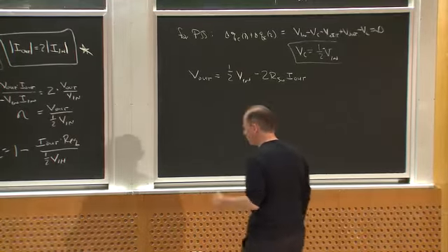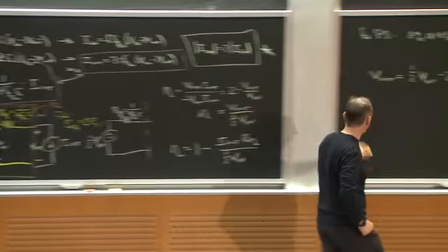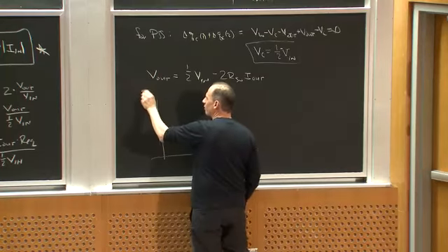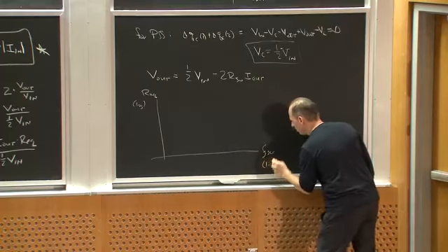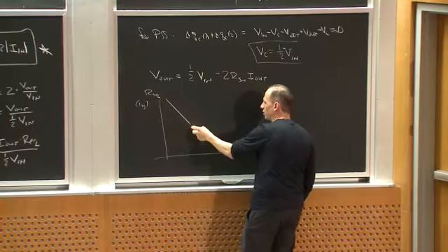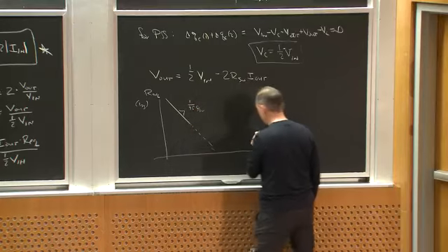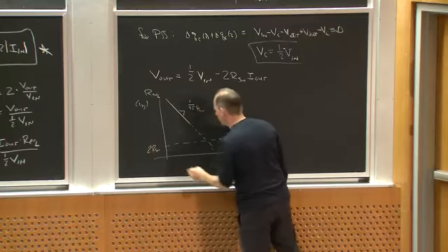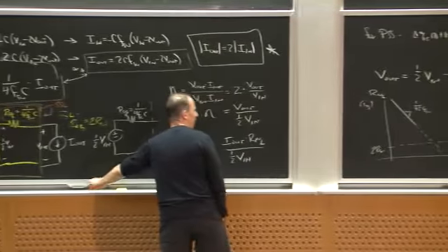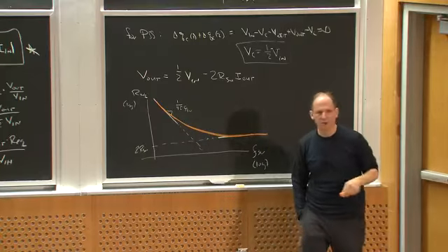Okay? So what happens in the real world is if I have a switch capacitor converter, and I say I'm going to have this model for its behavior, then if I plot R equivalent on a log scale versus switching frequency on a log scale, what I'm going to get is something that falls linearly. This is 1 over 4 C F switch, okay? And then it's going to have some minimum value, which is 2R switch, right? And the actual value you're going to get is going to do something like this. All right, so there's some limiting efficiency you can get to.